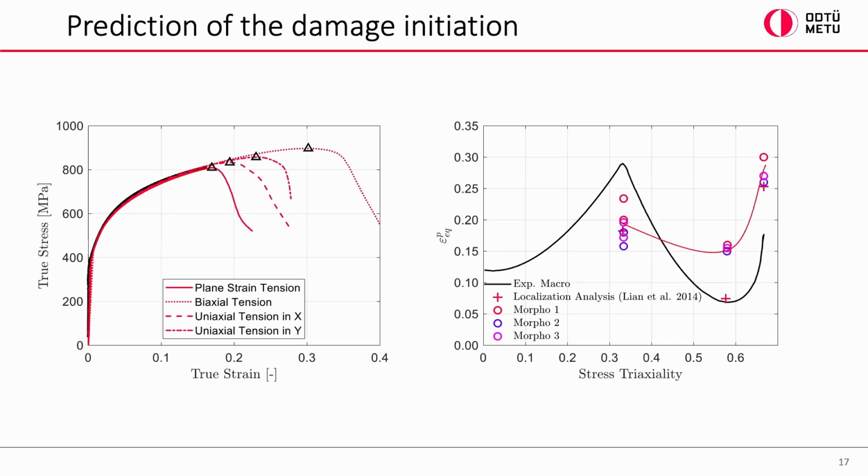Also we can improve this model, of course, by adding triaxiality or load dependence to the phase field model, but then we are also introducing another parameter identification phase to the model, which is not, of course, desirable.